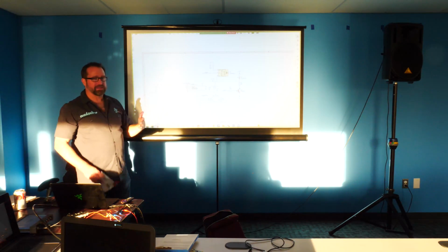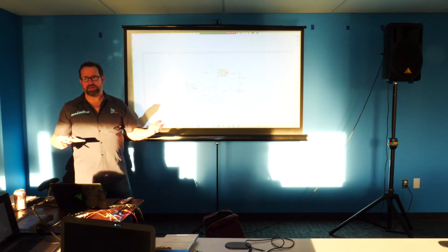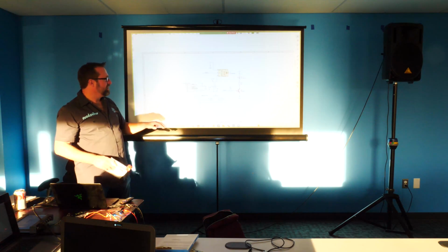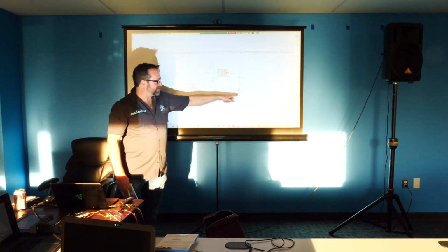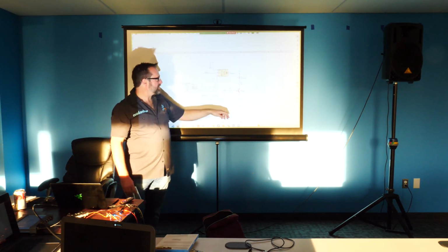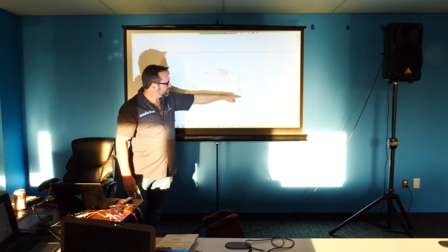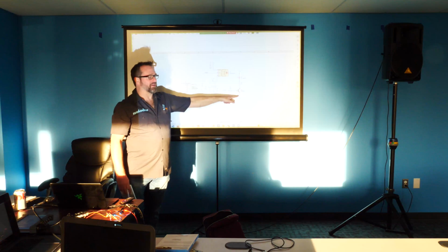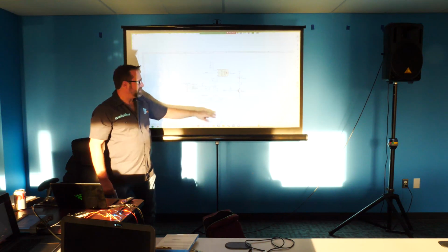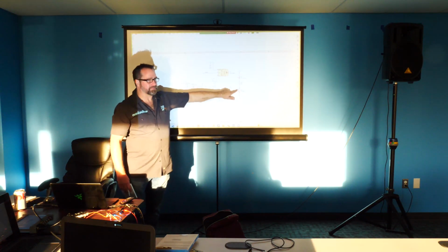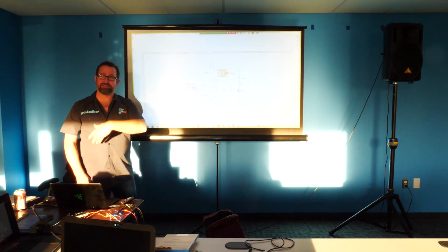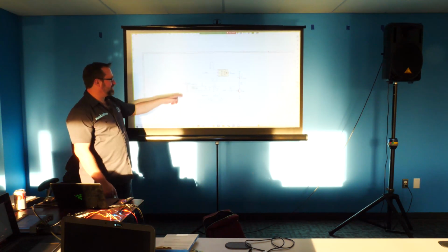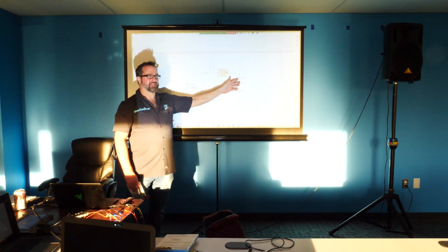Now, you might say, well, the Raspberry Pi Pico can't handle 5 volts. Well, the transistor kind of isolates it from that 5 volts, so the current path is just through this way, and there's no current that goes, or a small amount of current that goes this way, and then the voltage here is only a diode drop. Now that's electronics. You don't need to know any of that because we're just going to toggle this pin, and the magic's just going to happen.